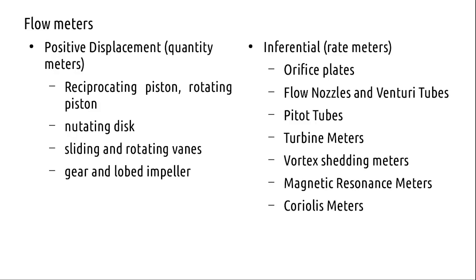So today we'll take up the Orifice plate. Orifice plate is an inferential type of flow meter, and the Venturi meter and flow nozzles are direct extensions. You would have even pitot tubes. They are used in aircraft to measure the air speed. On aircraft, usually near the front part, the nose cone part, there will be these pitot tubes, something which projects out. All these, in fact the first three of them, are directly based on Bernoulli's principle.